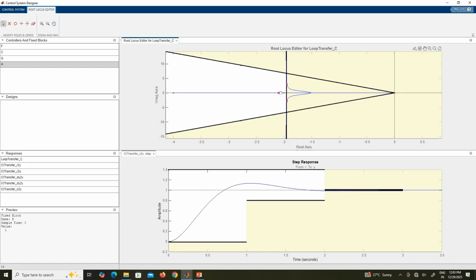Okay. So let me just hold on to the 0 a bit. The 0 has gone towards that side. Now you see, if I change, so this is where our output is correct. I am getting what I wanted to, right? You can see that 40% overshoot, the response has also got inside this band within 2 seconds.